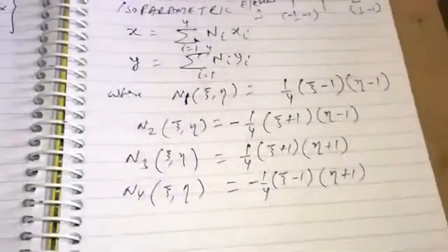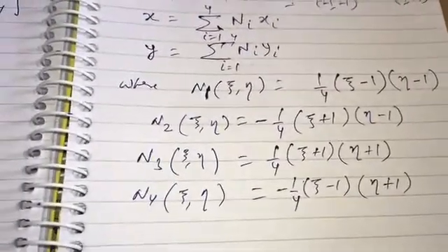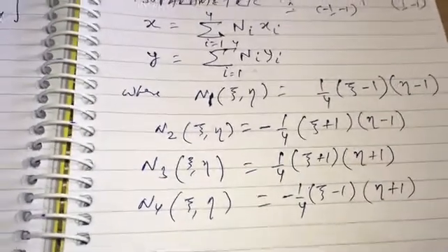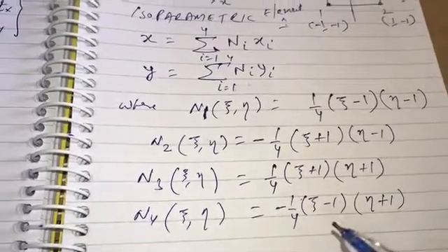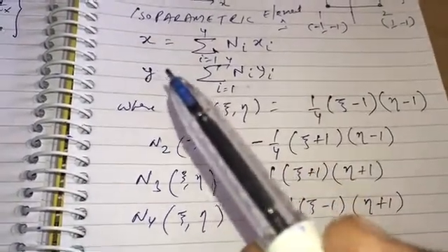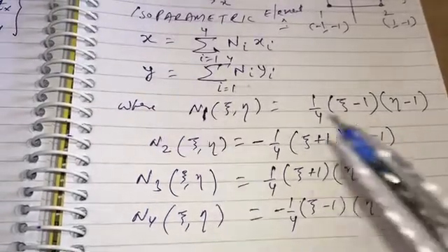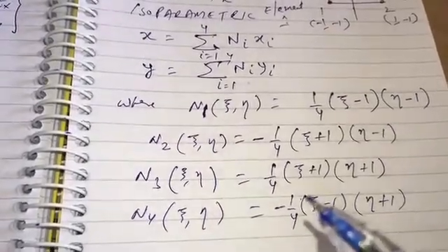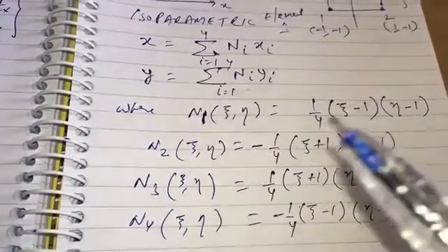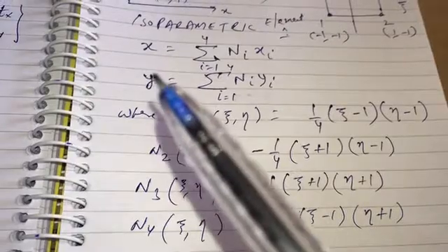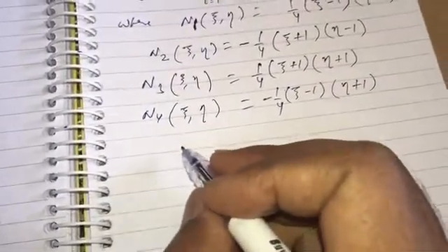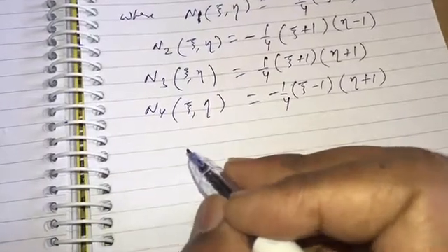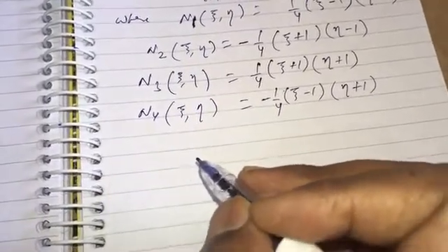Now, what I mean is N1, N2, N3, N4 are in terms of xi and eta, and x is related to this xi and eta. So there is a correspondence between x and xi, or from this coordinate system to this coordinate system. I am going to repeat what we have seen in the video lectures